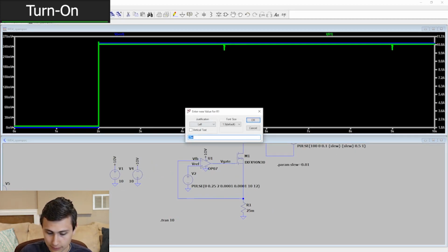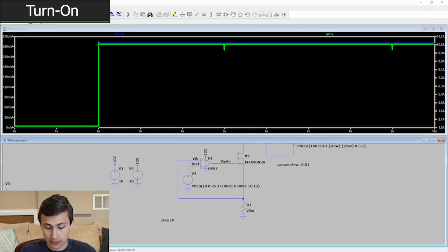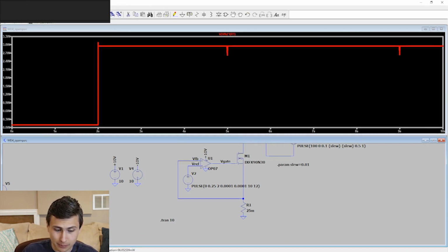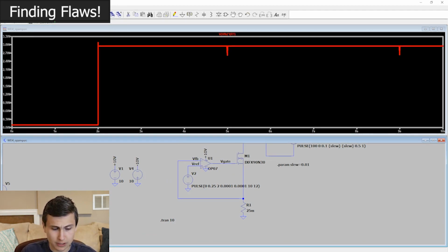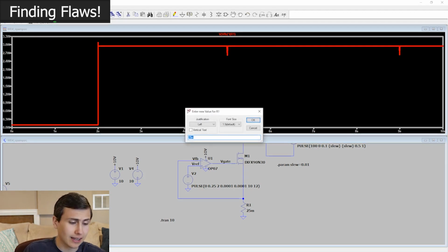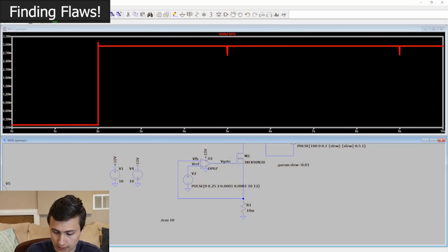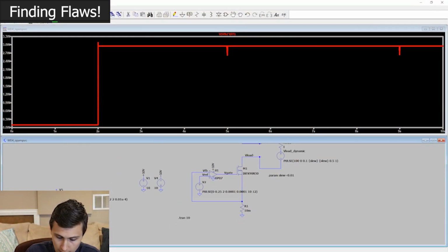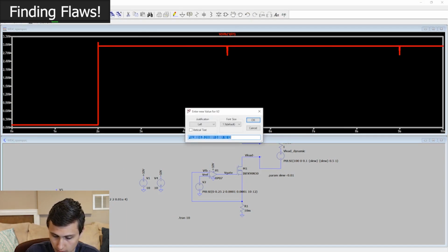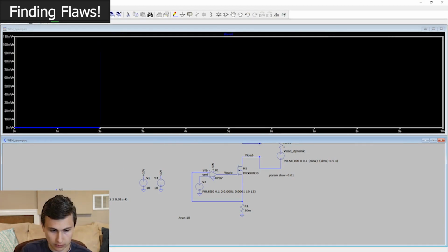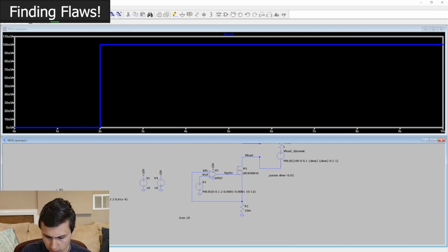Okay, so let's say, for example, we really wanted the circuit to work. The power dissipation in our downstream resistor is kind of a lot. 3 watts is kind of a lot. And if we put in a 10 milliohm resistor, like you do, and we change our current set point, so now Vref is up at 100 millivolts, our resistor is 10 milliohms, so we would expect the same current.